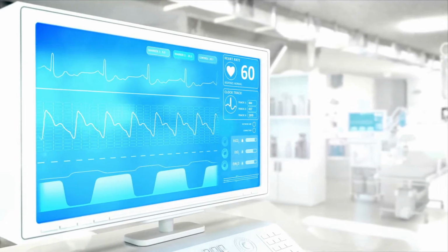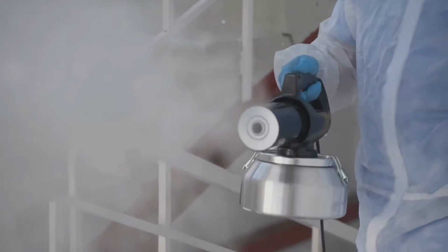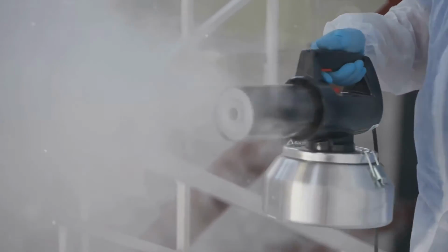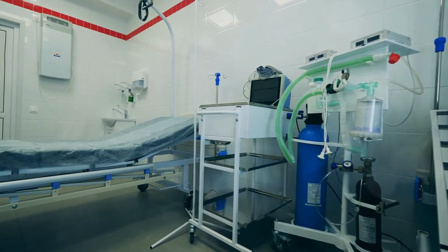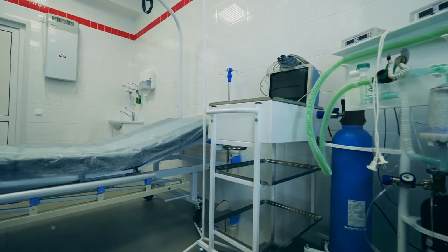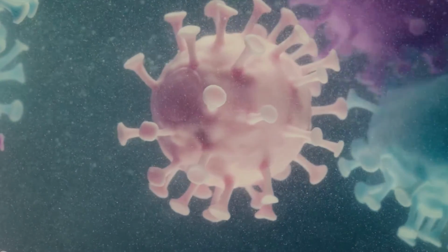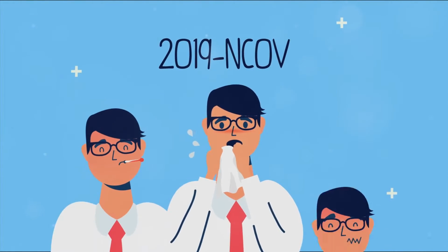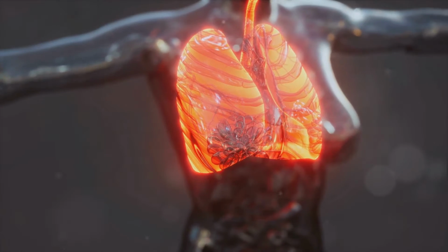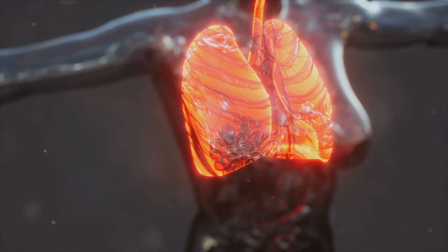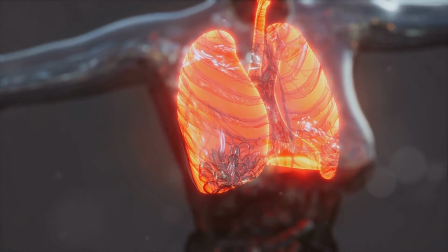In the context of healthcare, DPM can be utilized to model the behavior of airborne particles, such as those involved in the spread of respiratory diseases. This application is particularly relevant in designing hospital ventilation systems or studying the effectiveness of air purification technologies. The simulation process involves setting up particle injections to mimic coughs or sneezes and analyzing particle trajectories within different room configurations. Adjustments in airflow patterns, temperature, and humidity can significantly affect particle behavior, insights that are vital for infection control.